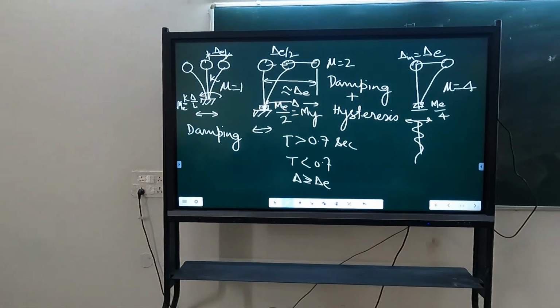Okay, sir. If the earthquake, let's consider earthquake force is coming 100 kilonewton. We have designed for this 100 kilonewton. This is for 50 kilonewton. Right. Even though you are saying that the displacement in this case and displacement in this case are equal, Right. I am saying that I am designing for this 100 kilonewton. If the 100 kilonewton is coming there, it will resist 100 kilonewton. After that 100 kilonewton, it will go in the plastic zone. Right. Okay. If you apply a higher earthquake, Higher earthquake than this. then this will also. Than this.